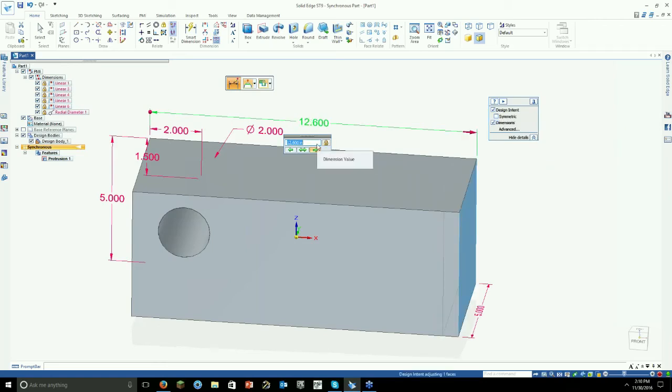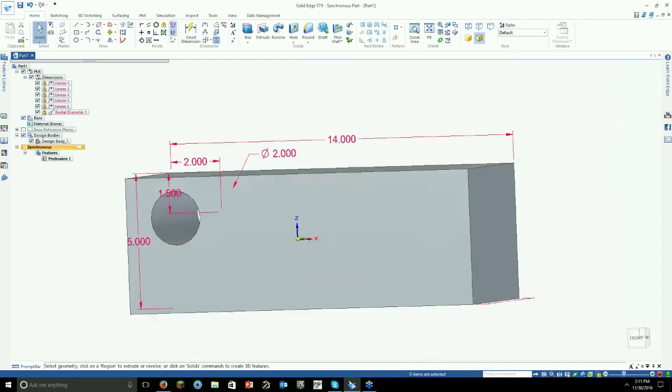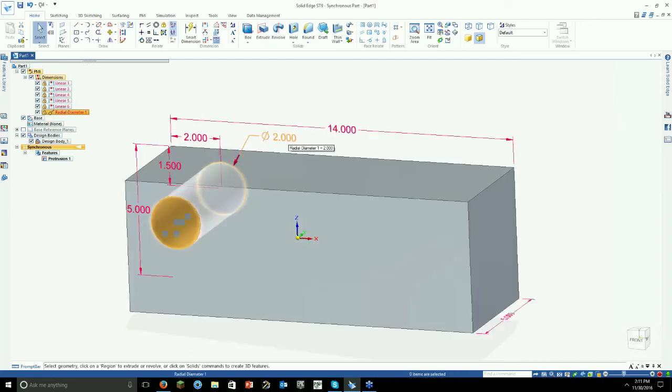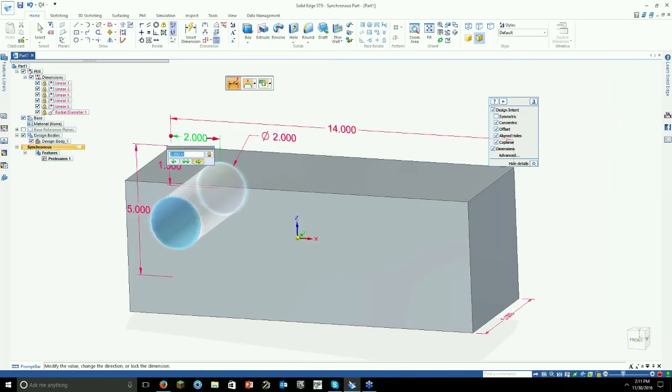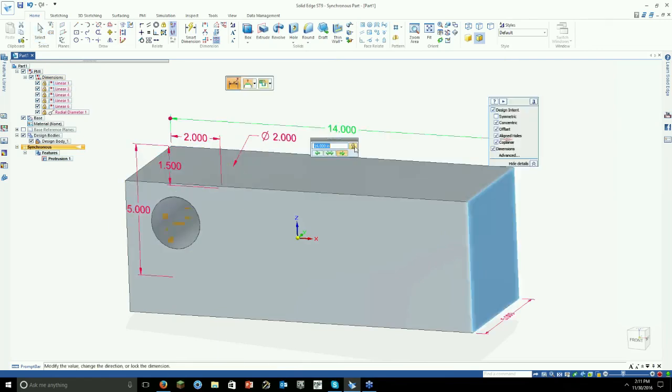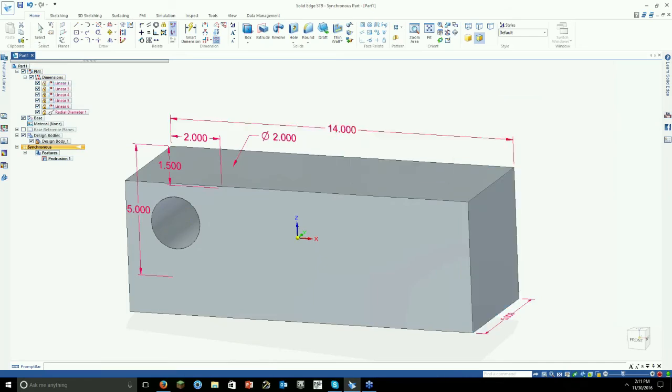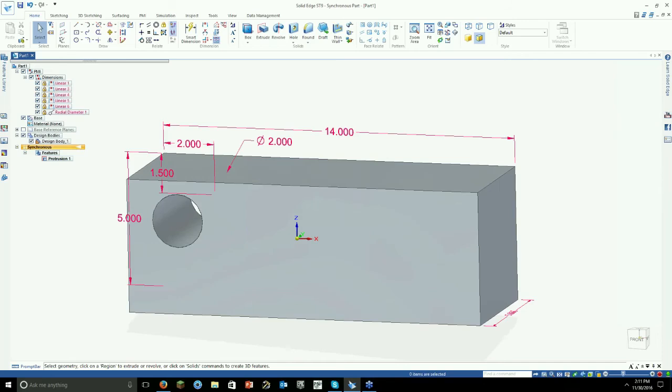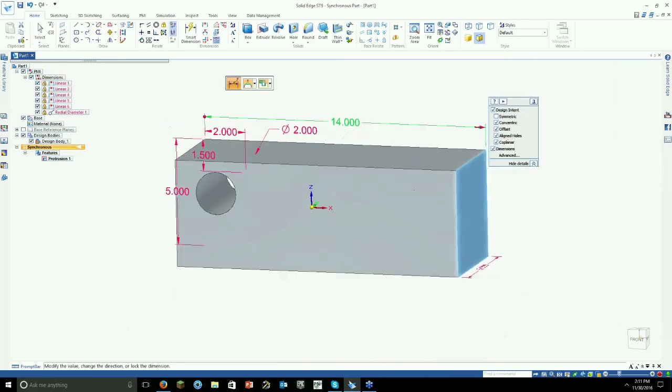Now you notice when I make a change, it's moving in the direction that I told it to, basically because I told symmetry to turn off. All right, there we go. So I typically like to lock the dimensions myself and go through and just click and unclick, lock to, or just again, to lock it, you just click it, pick the direction you want, lock it. That way it always remembers the last face that you selected is always going to be the face that changes.